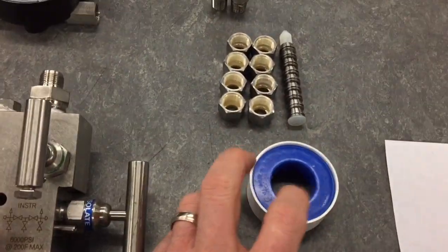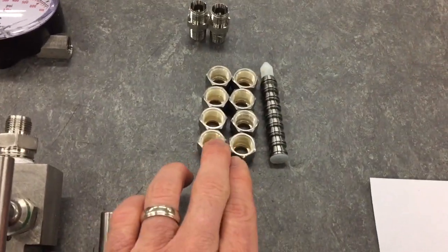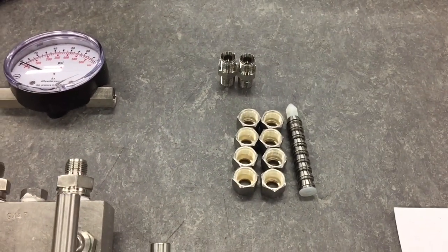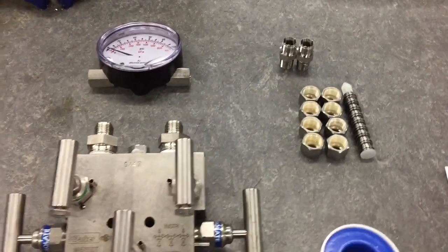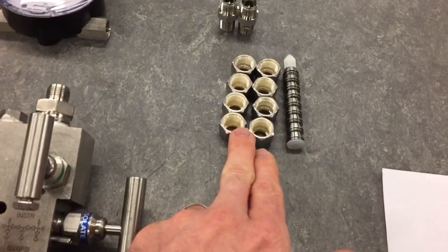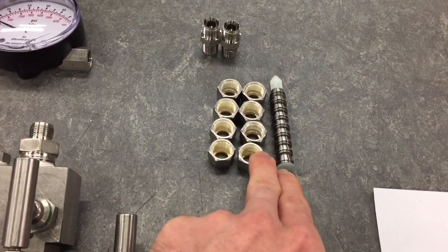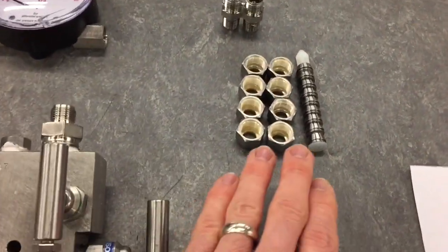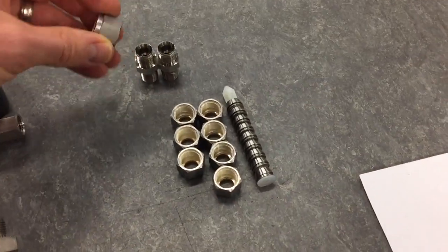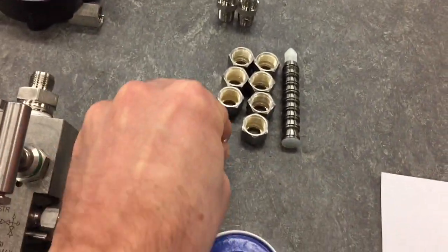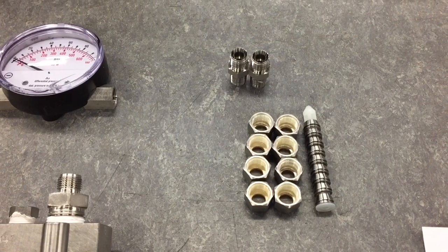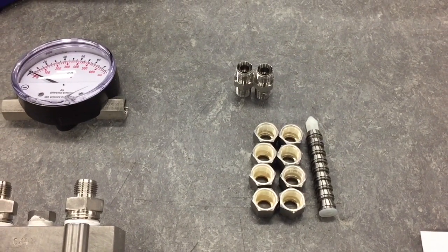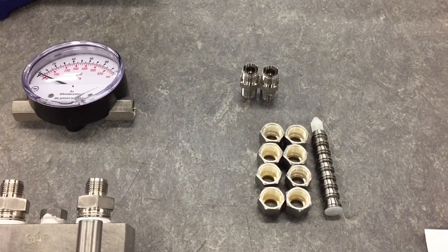So I have all the nuts that we require for the lab. We need 8 nuts. When we're done with the lab, we're going to be cutting the nuts off the tubing and reusing them for the groups who will be performing the lab after. With each one of these nuts, we need to have a ferrule installed, so all of the nuts will need that installed. I left them out. Usually when you purchase a fitting, the ferrule will already be installed and the nut will already be on the fitting, but I wanted exposure to that so we have the ferrules installed correctly. So what I'm going to do is get a ferrule installed on one of the fittings so I can show how a ferrule should be placed in these nuts.